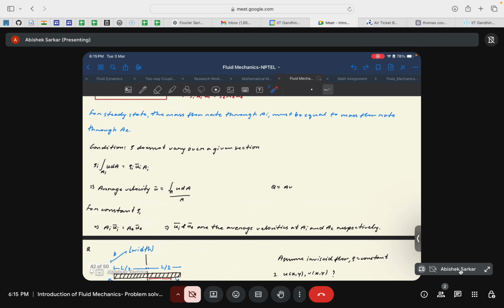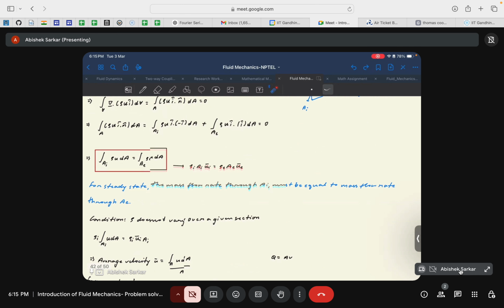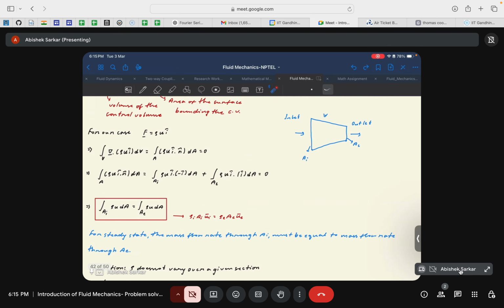And the average velocity basically helps us know the order of magnitude of the velocity across the cross section. It might happen that the velocity at the edges is lower than the velocity at the center line, because of the no slip boundary condition, and you will see that eventually the velocity profile turns out to be of this form.